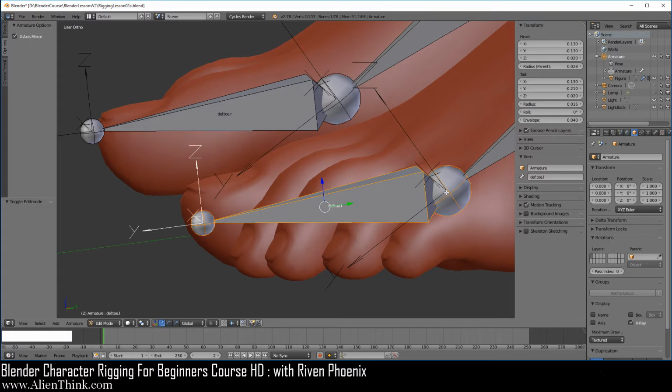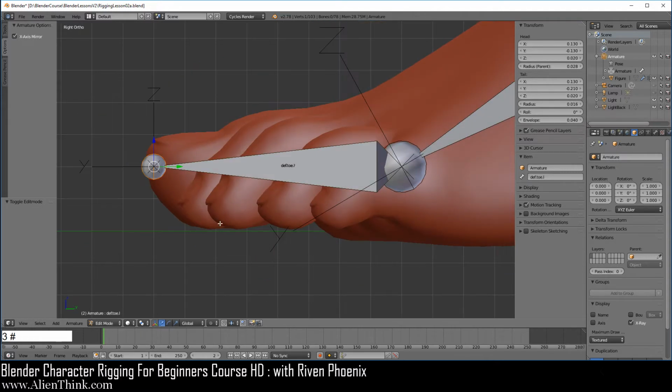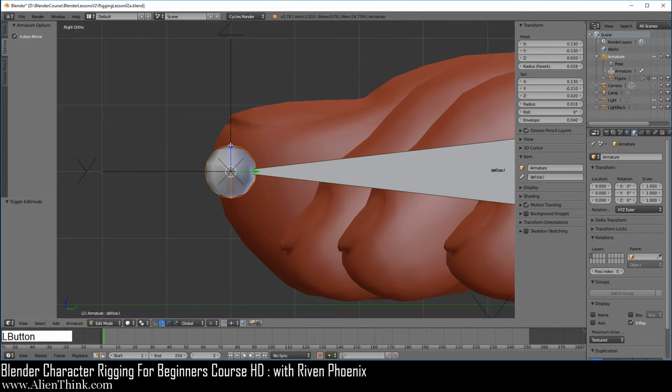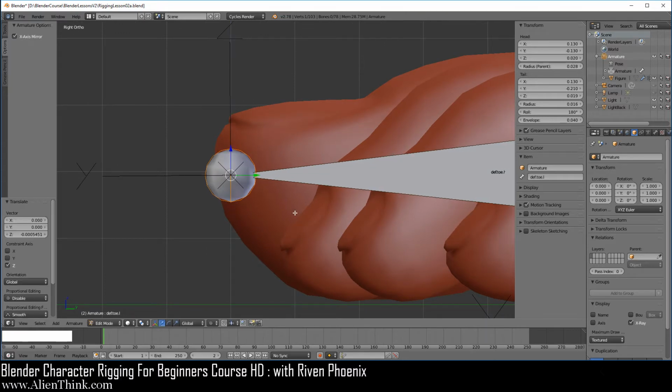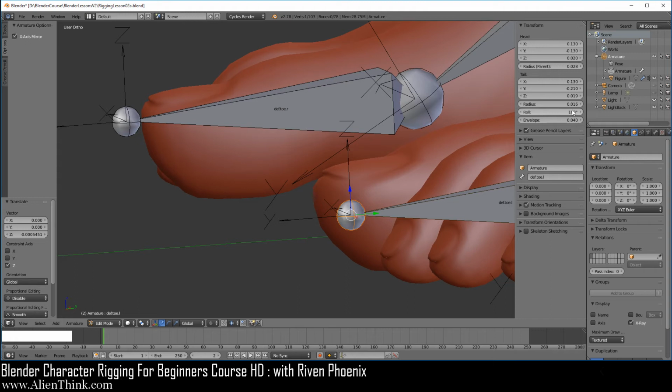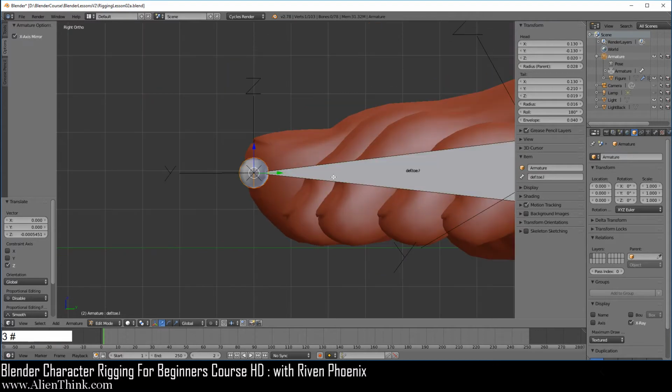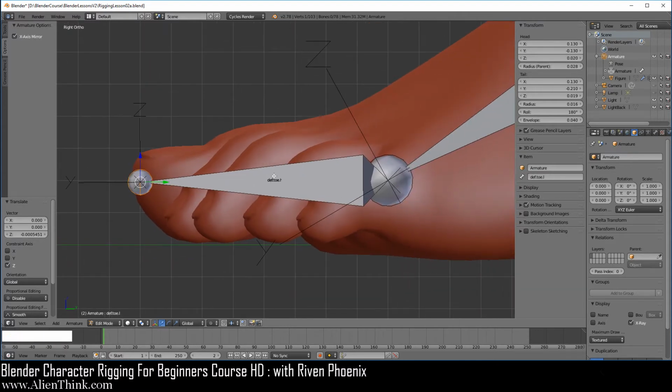Now we didn't have to do this, right? We didn't have to copy the z onto the z of the tail. If you click on the tail over here, press the 3 key and actually move this down just a little bit, you'll notice that in order to point now the z up, we have to type in 180 rather than 0, right? So if you type in 0, now the z is pointing down. Okay, so over here, if we type in 180, it'll point up, but it's not perfectly horizontal, and that's okay. This is because this is an organic figure. It's not a machine, right?